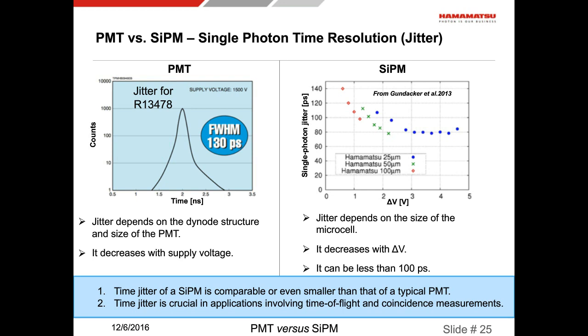One can therefore make a statement that the jitter of a SiPM is quite comparable, perhaps even better, compared to the jitter of a typical off-the-shelf PMT. Of course, it's no match to a specialized PMT for very small jitter. But if I, again, randomly pick two devices and compare the jitter, SiPM is very comparable, again, if not better.